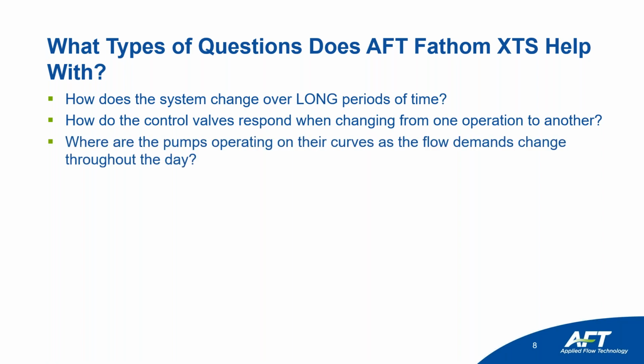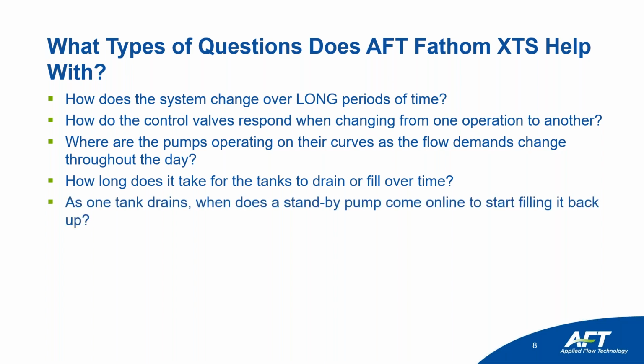Another example is how are the pumps operating on the curves as your flows change throughout the day? How long does it take for your tanks to drain or fill over time? That's a wonderful advantage of using Fathom XTS, because with Fathom XTS, your reservoirs can be a lot more sophisticated and model actual finite tanks, either open tanks or closed tanks, and that's how you can track the liquid height change over time.